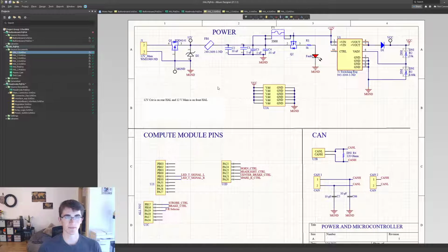So whenever there is a battery protection system fault saying that maybe one of our battery modules is over voltage, under voltage, or over temperature from outputting current too high, or maybe there's an issue with our batteries, this BPS strobe will flicker. And so what's interesting, if you think about it from what I said in my last video, is our BPS system, we use an auxiliary battery pack before pulling power from our main battery pack, which is over 1,000 lithium ion batteries.